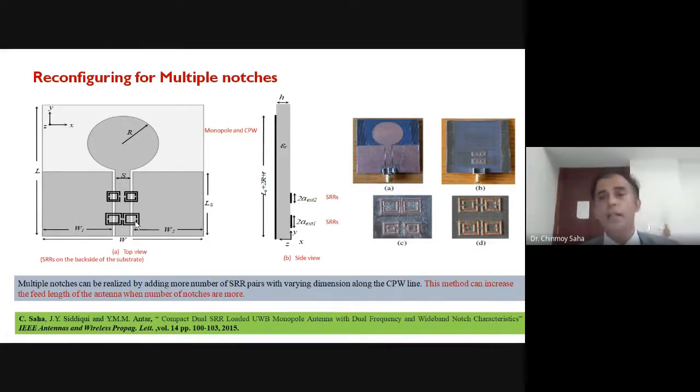So for that, as you can see probably from here, you have a couple of resonators here and another couple of resonators here. Here their sizes are rapidly varying. Whereas in this case also 2 pairs are there, pair 1 and pair 2. The size difference between pair 1 and pair 2 is very small here. There is a subtle variation here, and there is a coarse variation here. So these will correspond to two different resonances which are pretty isolated. And in the second case, the resonance frequencies will of course be different, but they are very close to each other.